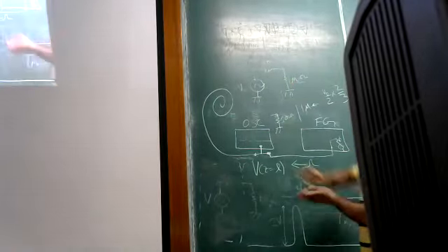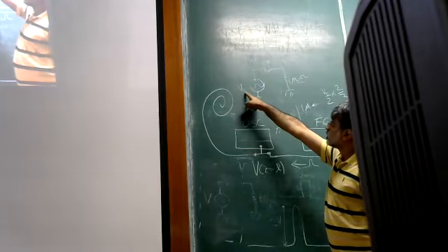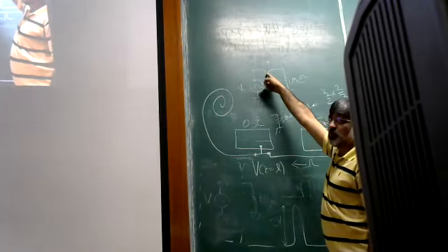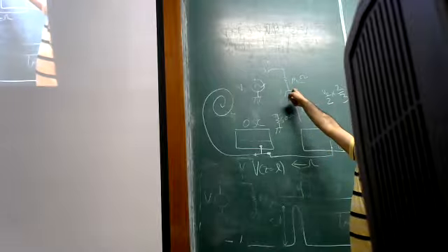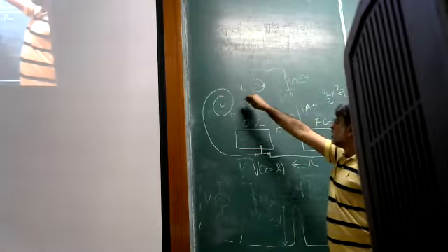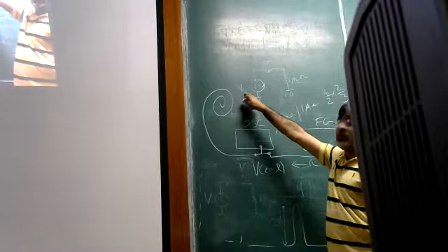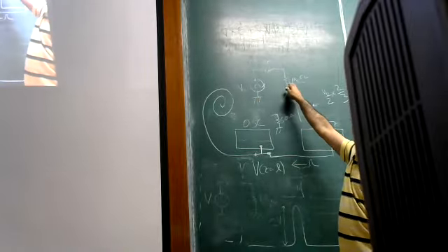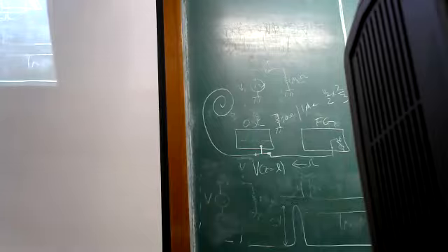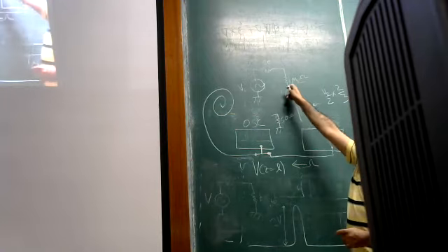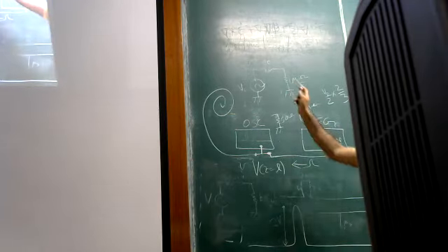If you have a voltage whose ideal voltage source amplitude is V0 with a 50 ohm source impedance, and you measure the drop across a 1 mega ohm, you will measure V0. If you have 50 ohm, you measure V0 over 2. The instruments, because they expect in most cases you're working with a matched load, rather than you having to keep in mind this factor of 2, allow you a setting where you can tell it, are you going to put high impedance loads or are you going to put matched loads?